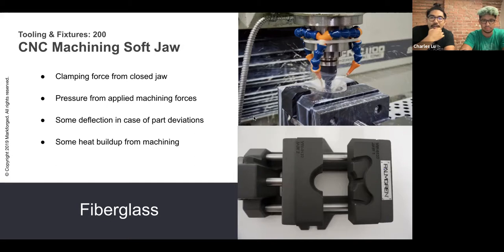could do this implementation. We've shown here the soft jaw that is clamping two strangely shaped sides. I would say that in some cases you may want to machine one side, right? You can have the conformal side, the difficult side, and not machine that. You can print that, and then have the side where you put your datum maybe on the simpler side, right? So on the left side down here, that seems like a pretty easy pocket to mill out.